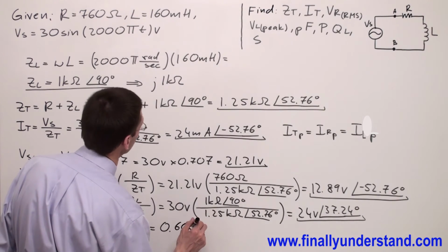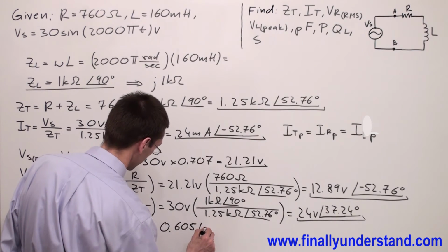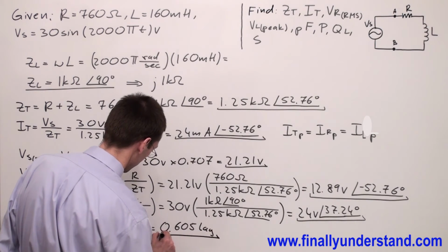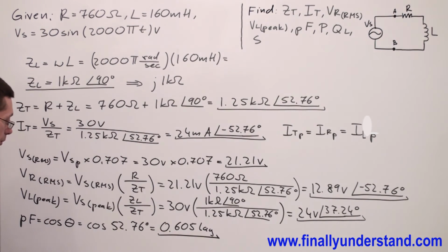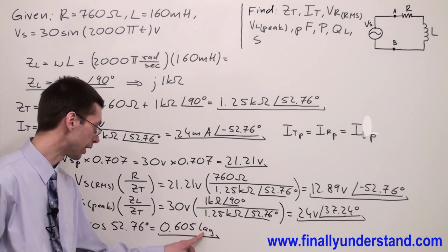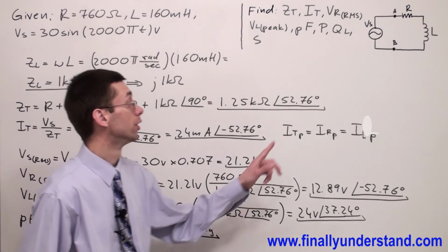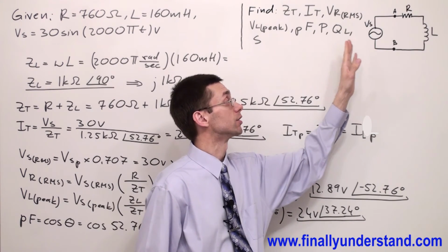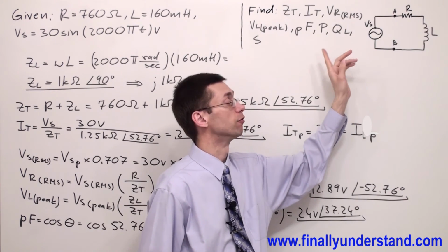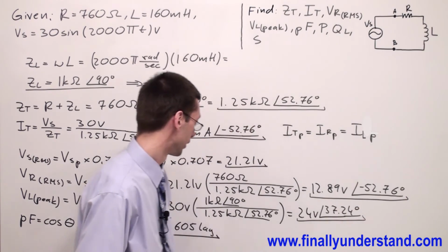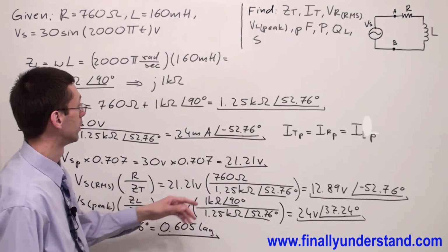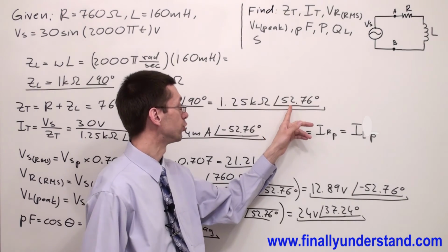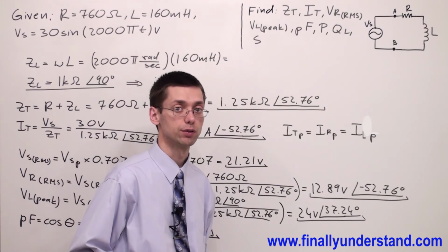0.605 lag. Okay, so I have lag because the current in the circuit is lagging the voltage source by the angle of 52.76 degrees.